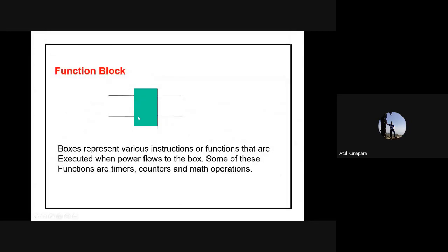Then there are some inbuilt function blocks also available in your PLC software, like timers, counters, pulse timers, or logic comparison tasks such as less than and greater than. So there are various types of functions already inbuilt in your PLC software, so that you need not program that logic yourself. You can directly use the function block. That is possible in the PLC.